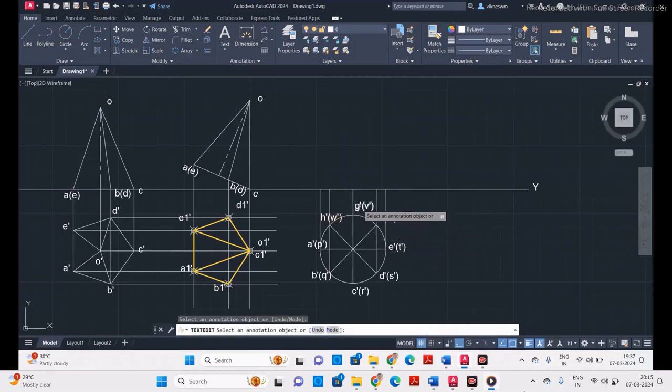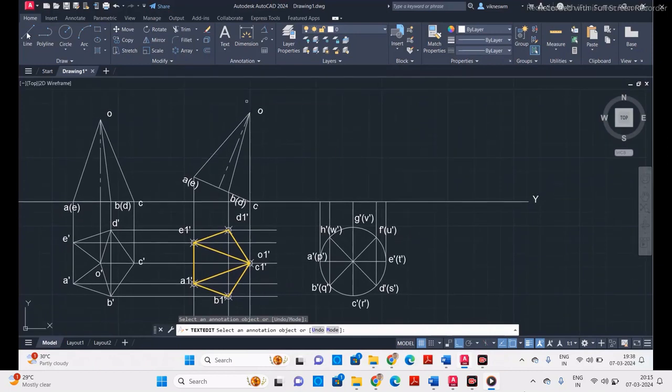So I defined all the bottom face corners. Now take a line and mark that axis length. This is the height of the cylinder at the front view. The axis length is 70 mm. From all the projected lines, draw a vertical line for 70 mm.